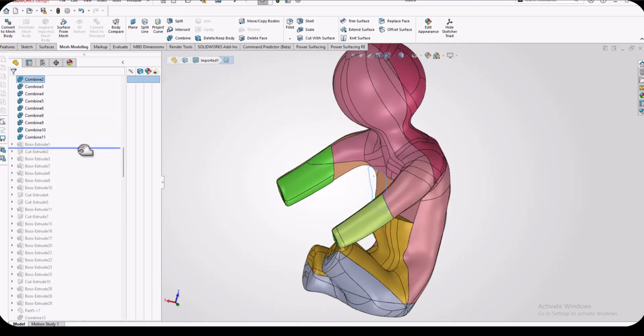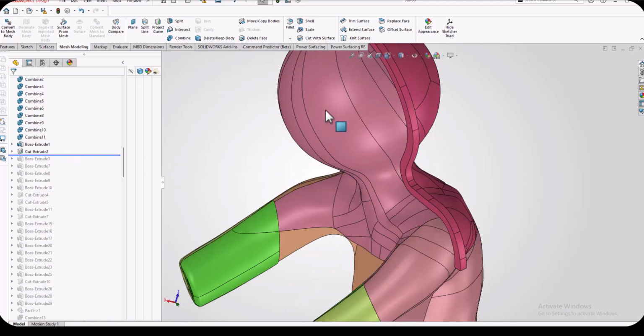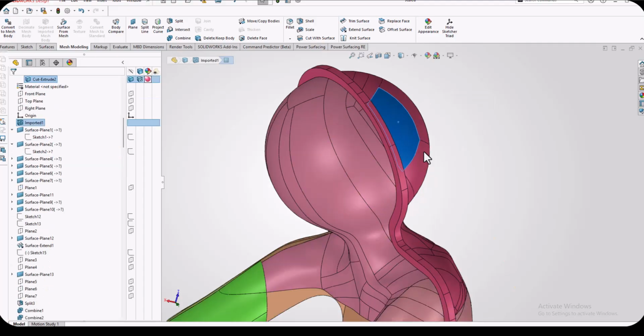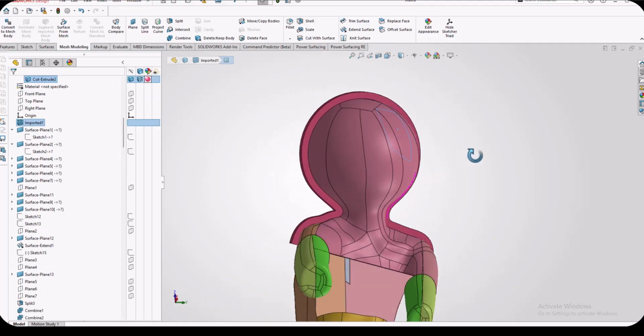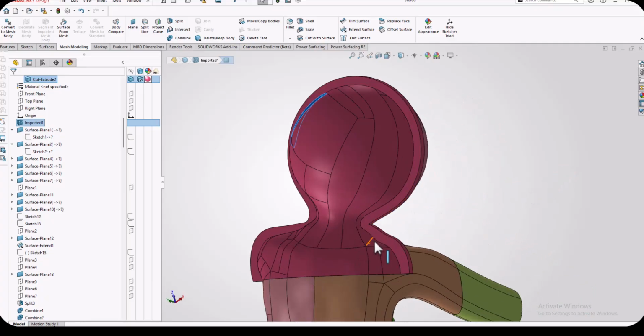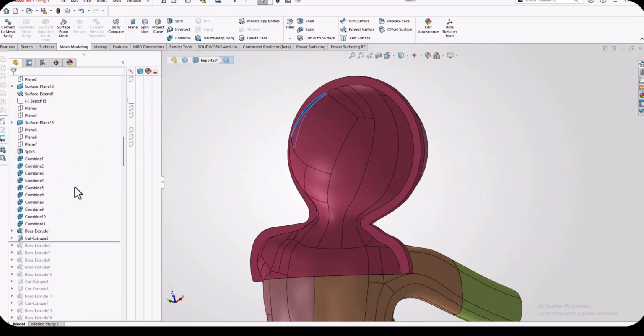After that, I created a series of extrusions around the mold pieces. These extrusions form the connection flanges around each mold section. These flanges are used to connect the mold pieces together. As you can see, I created these connection flanges piece by piece.